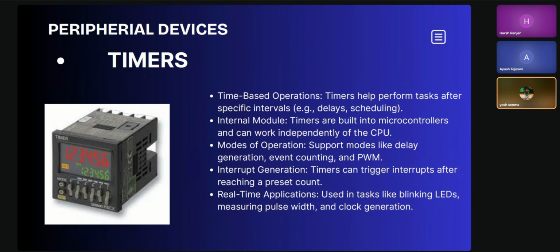We configured the prescaler to scale down the clock speed, and used the interrupt flag to trigger an event when the timer overflows. We used polling and interrupt based approaches interchangeably. Without timers, we are forced to use delay loops, which are blocking and not efficient. Using a timer gives us realistic behavior just like a real appliance.